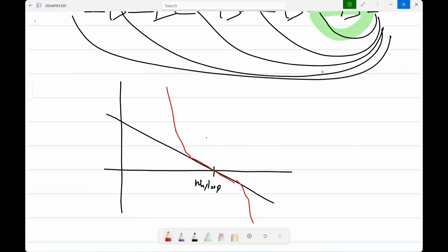So this is yet another way of simply saying that the Nyquist plot should enter the unit circle in the third quadrant. And the block diagram way of looking at it is that around the unity loop gain frequency, there is actually only one stage that is relevant, that is active in the feedback loop. So the bottom line is we can only have one stage with stability, and that's what we'll eventually have.